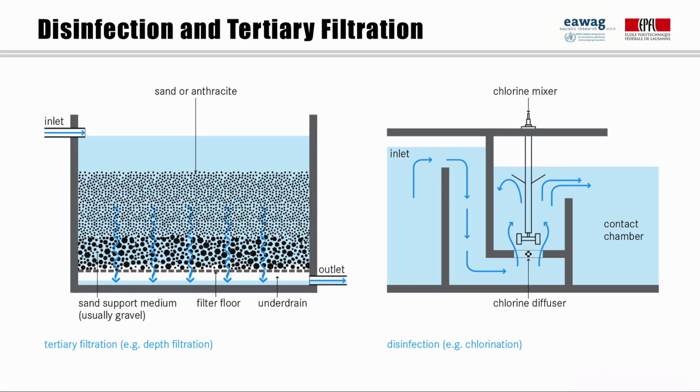On the other end of the treatment process, there are different possibilities to polish the effluent, the so-called post-treatment technologies. Depending on the desired end use of the effluent or on national standards for discharge and water bodies, a post-treatment step may be required to remove pathogens, residual suspended solids, or dissolved constituents. This can be mainly achieved through tertiary filtration and disinfection techniques.